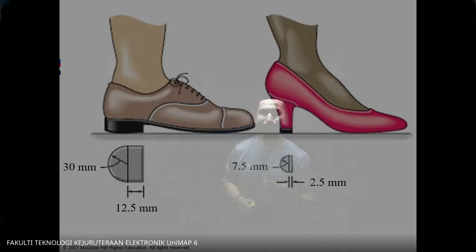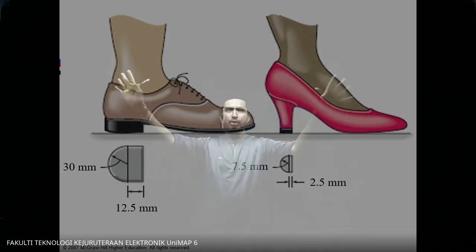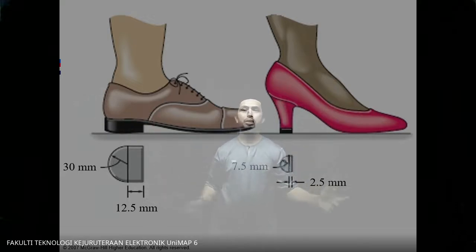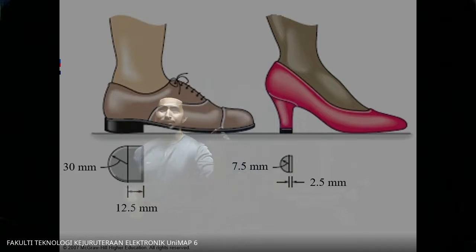Can you help me? Okay, now, without looking to the notes, just by your understanding on my lecture, can you calculate the stress for both condition? Stress equal to force divided by area. Make sure you convert millimeters into meter.